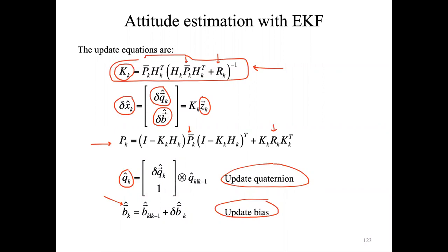For example, yesterday we have seen that if you have a measurement frequency rate at 10 Hertz, so you have 10 observations per second, you're able to have 10 corrections of the bias every second. So you're able to detect the time variation of the bias and so the drift.